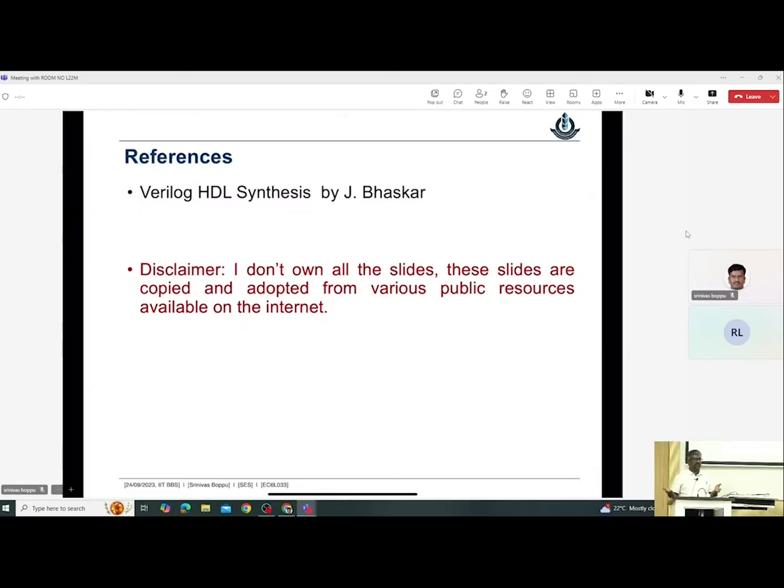And there are some golden rules. In modeling combinational logic, use only blocking; for sequential, use only non-blocking. Use always blocks even for combinational logic, and list all the right hand side variables in the sensitivity list. Always blocks have the advantage of advanced constructs like if, else, case, which we can use. If you use assign, you should only use long expressions, but that's how it is.